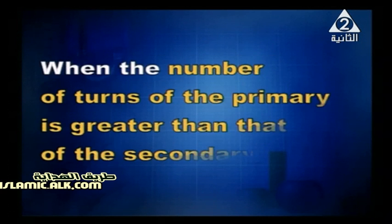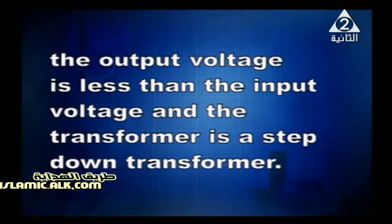When the number of turns of the primary is greater than that of the secondary, the output voltage is less than the input voltage, and the transformer is a step-down transformer. So when Np is greater than Ns, Vp will be greater than Vs, and the device is a step-down transformer.